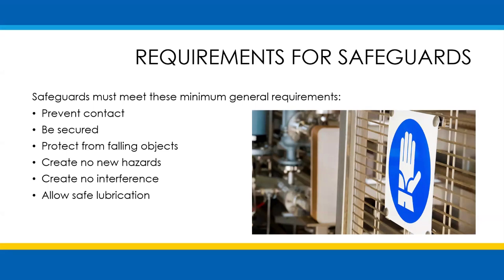Any safeguard which impedes a worker from performing the job quickly and comfortably might soon be overridden or disregarded. Proper safeguarding can actually enhance efficiency as it can relieve the worker's apprehensions about injury. If possible, one should be able to lubricate the machine without removing the safeguards. Locating oil reservoirs outside the guard with a line leading to the lubrication point will reduce the need for the operator or maintenance worker to enter the hazardous area.